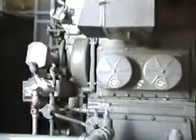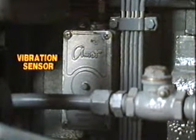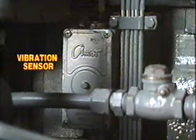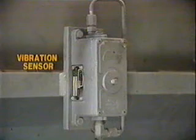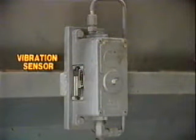Vibration sensors are located on the compressor and sometimes on the prime mover. If excessive vibration occurs, these sensors send a signal to shut down the compressor. Operators should immediately report any unusual or excessive compressor vibration, because this often signals a major mechanical problem.